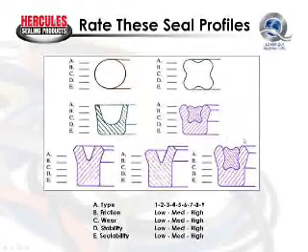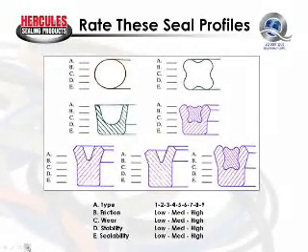But you could not use this particular seal in a low-pressure application where you have to overcome a lot of frictional drag. So it gives you a little bit of idea of how to analyze different seal performance. And remember, this is only true for low-pressure applications, low-pressure situations. If it's high pressure, all of these shapes seal effectively. It's only at low pressure that the seal shape affects seal performance in a sealing application.